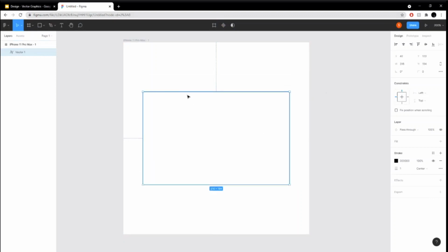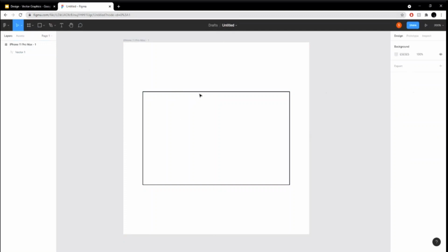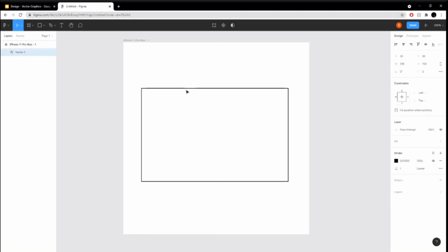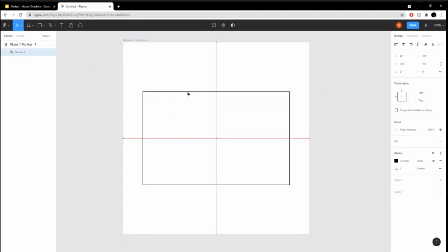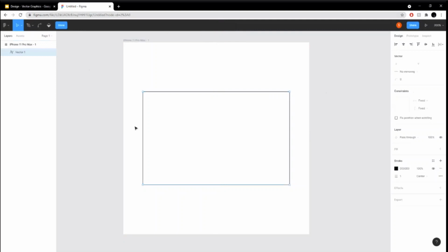In order to edit this, you may say, "Wow, this doesn't look like a mail icon," and I agree with you. In order to make more edits, you have to click this button right here. It says Edit Object, the first one in the top middle of your screen. You can click that, or you can press Enter, and that'll put you into vector edit mode.